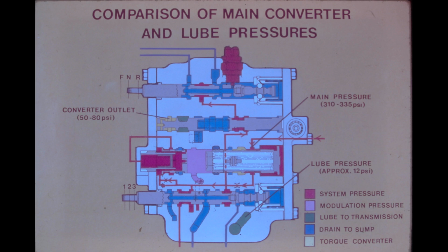A weak spring behind the converter regulator spool would cause a reduction of converter pressure at low idle. A broken spring would cause a sharp pressure drop and would also cause the neutralizer spool to remain activated after it was applied.